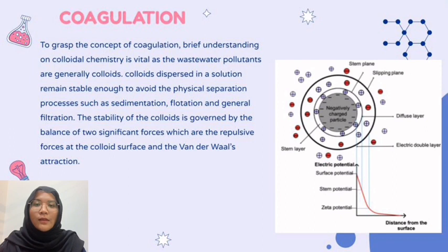To grasp the concept of coagulation, a brief understanding of colloidal chemistry is vital as the wastewater pollutants are generally colloids. Colloids dispersed in a solution remain stable enough to avoid the physical separation processes such as sedimentation, flotation, and general filtration.